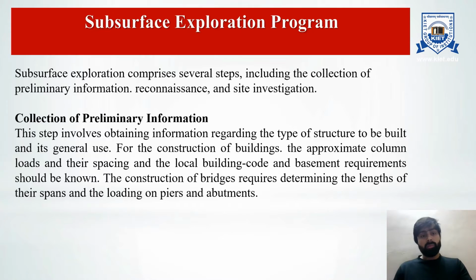Subsurface exploration program. Subsurface exploration comprises several steps, including the collection of preliminary information, reconnaissance, and site investigation. Collection of preliminary information: these steps involve obtaining information regarding the type of structure to be built and its general use. For the construction of a building, the approximate column load and their spacing, the local building code, and the basement required should be known. The construction of a bridge requires determining the length of the span and loading on the piers and abutments, etc.